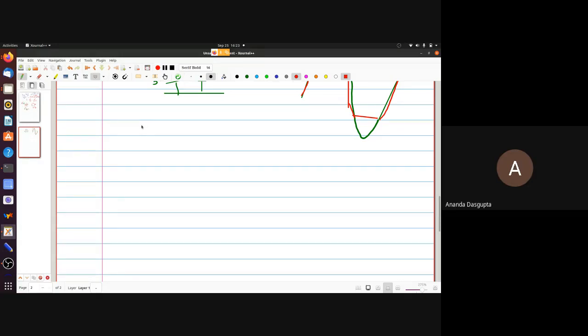You should realize that the current, of course, will be voltage across the capacitor by R, right? Because what you have is a diode on this side, but the diode is reverse biased, so this input side is cut off. You have a capacitor here, and you have a resistance. And once the input has declined below its peak value, the capacitor, which had already charged to the peak value, now slowly loses the charge through this resistance.